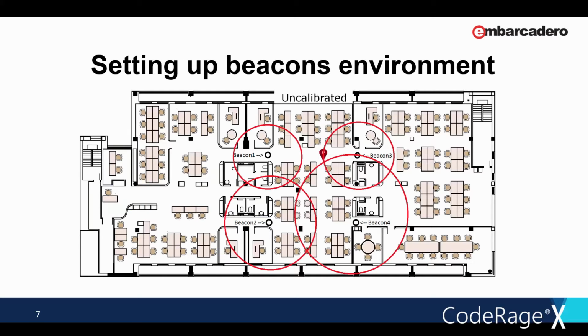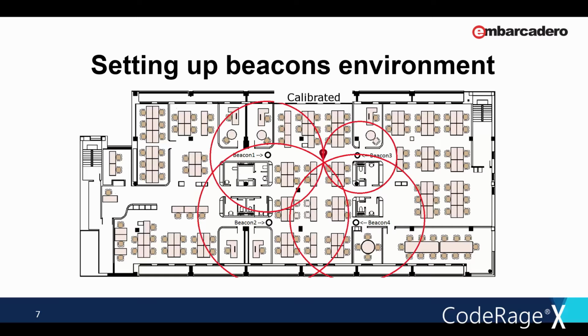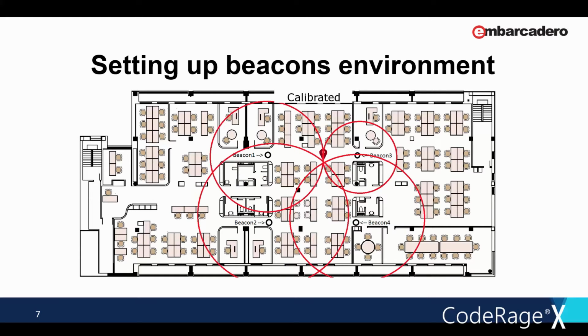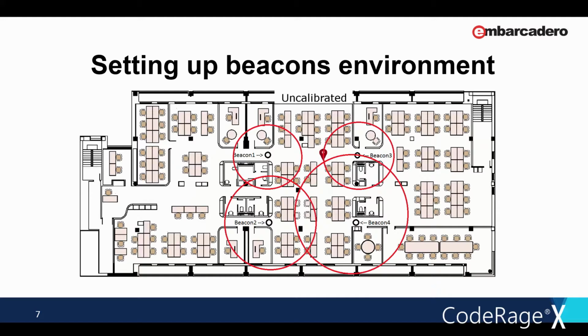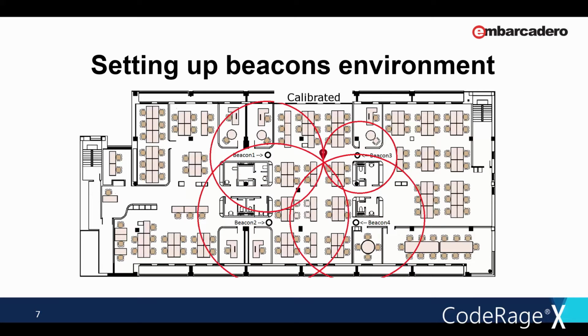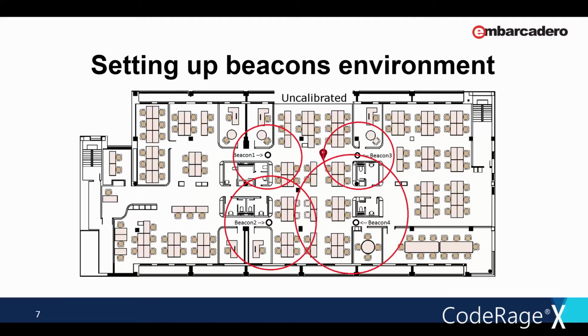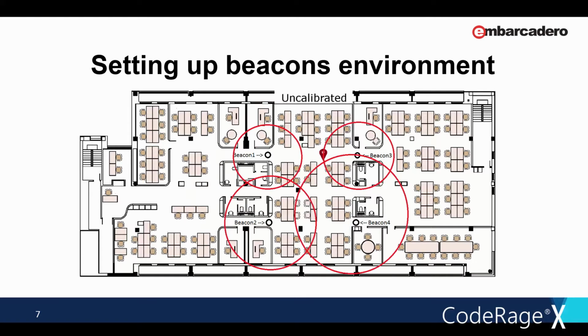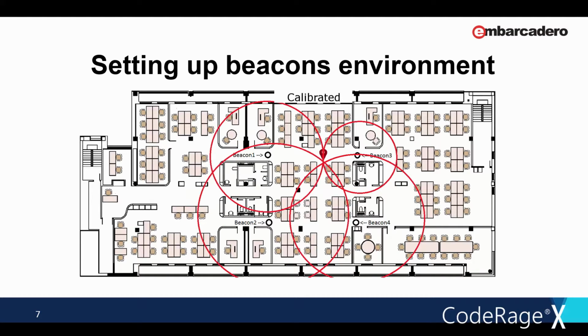The first and most important of all steps is the beacon calibration. The calibration of the beacon TX power. A beacon transmission includes a transmitted power field that indicates how strong the signal should be at a known distance. Beacons must be calibrated by measuring the signal level, RSSI, at this reference distance and then configuring the beacon to transmit this reference value. Without a proper beacon calibration, we can get a really wrong estimated distance, resulting in a mistaken position estimation, mainly because the algorithm can take a distant beacon as a nearby one and vice versa.